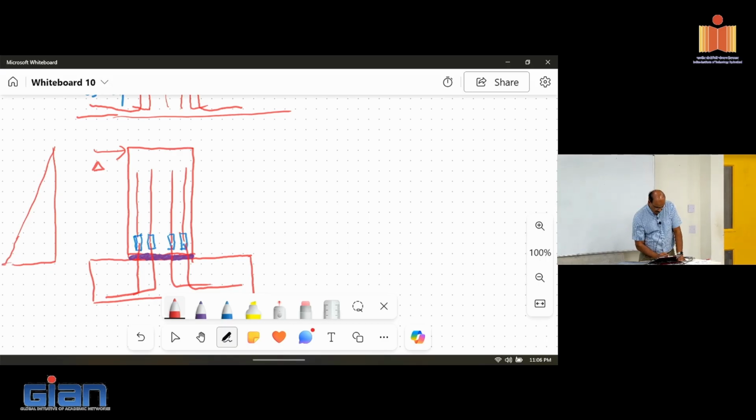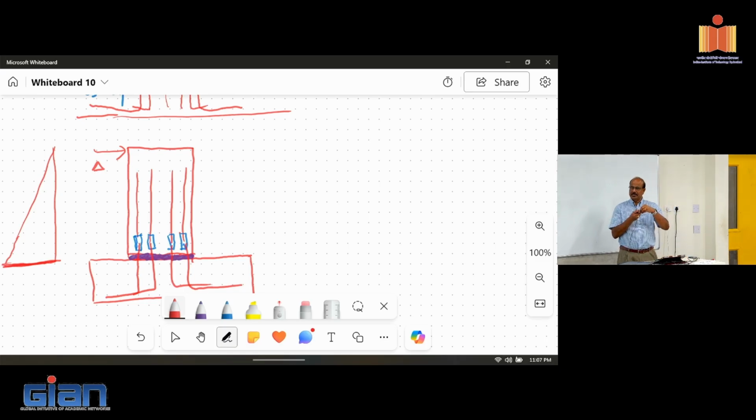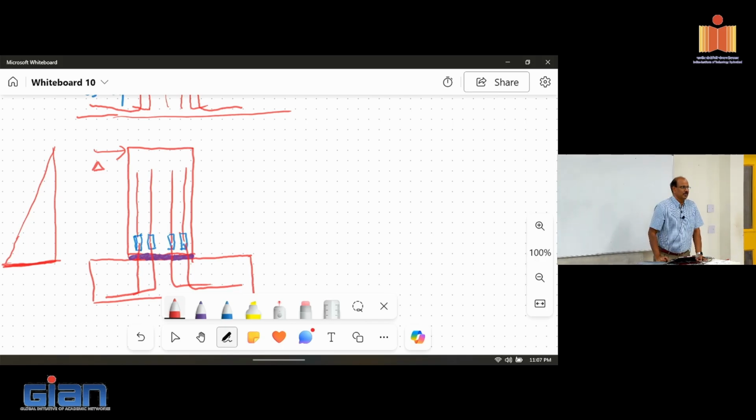But if you look at it, your moment is actually maximum at the base. I know several of you started putting cracks up here, but this area is going to be the highest moment. And if you don't have any couplers crossing the foundation interface, then that area is very likely to develop the first crack.